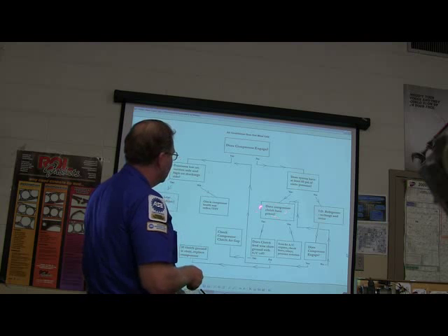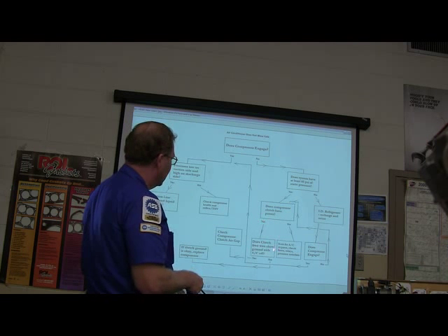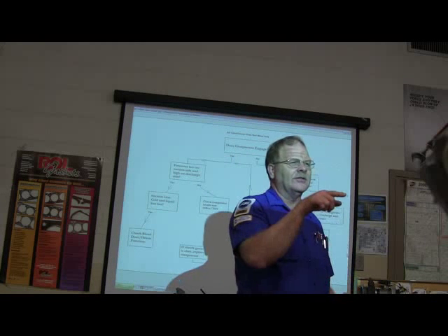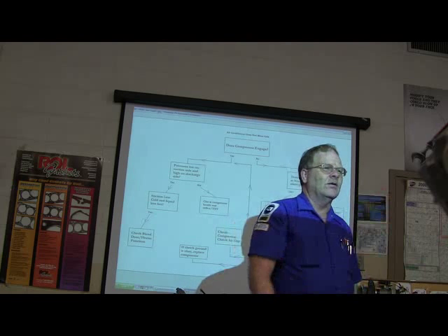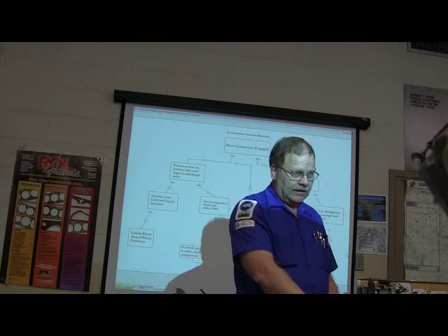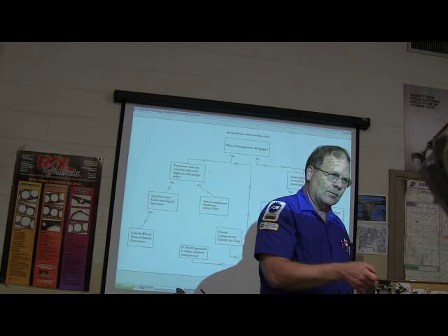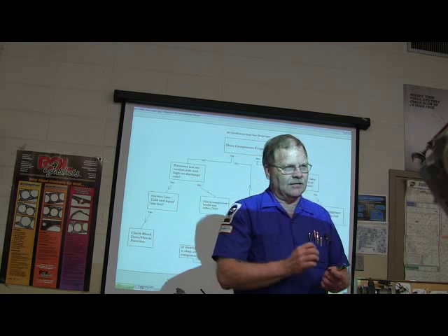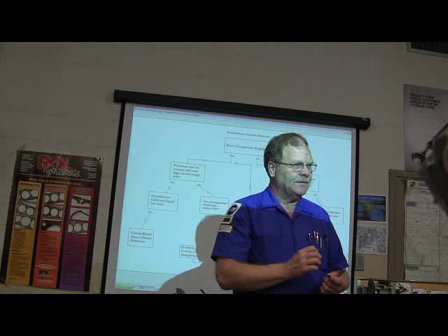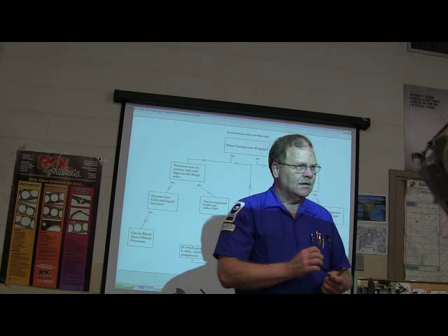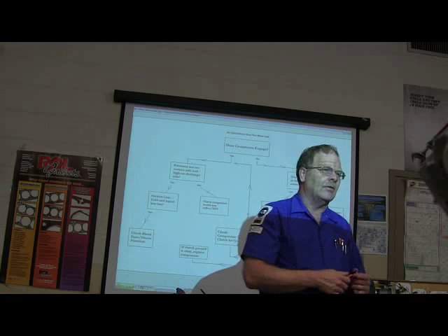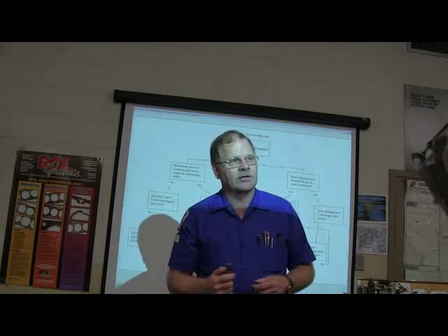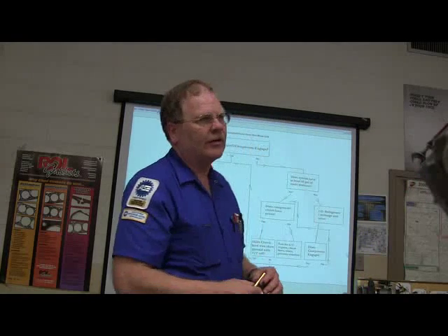All right, what's this? Does the compressor clutch have power? Yes. Does the clutch feed wire show ground with the AC off? What does that mean? You remember the Altima? Who worked on the Altima? Did you do that? Okay, get the Altima here, and we found the wire that was going to the compressor clutch, and we pricked into it with our little prick tool, and we turned everything off, and we hooked the test light to the hot side, and we wanted to check and see if there was power showing in that compressor clutch wire. And there was not, right? And what would be wrong with that one? Clutch. The clutch was bad. That's more expensive than putting a whole compressor on it, so we popped a compressor on it, and she was cool as a cucumber for about $325.